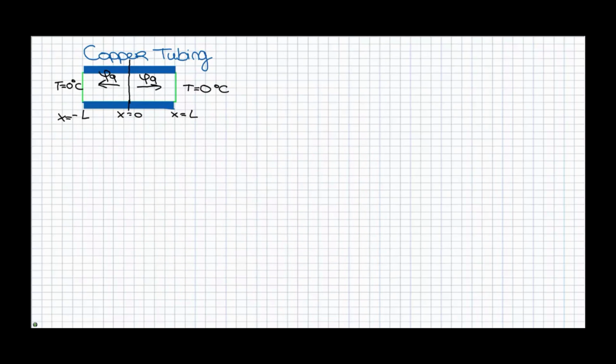Heat is produced in the tube and we would like to investigate in this question the temperature profile in the tube wall due to this heat production. For a first rough estimation we assume the tube to be a flat plate, as I already made a sketch of. They give the length of the tube, that it's 0.5 meters, so half of the tube is 0.25 meter.